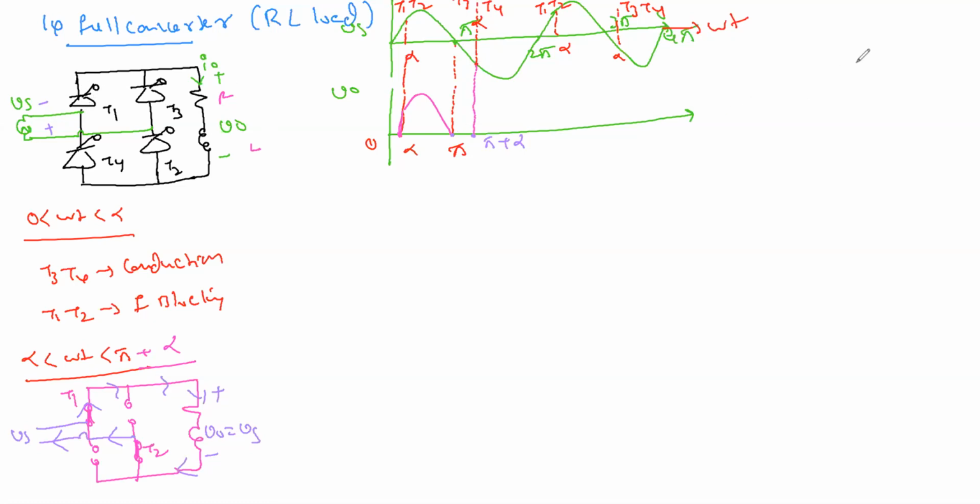With the inductor, we have seen this only if the inductor is taken. Look here now, one SCR complete, inductor is taken here. Now what we have observed? This is Vs, V0. V0 is a sine waveform which is Vs. After pi also they go into conduction. That's what I told you, beta is 360 degree for an inductor. Understood? 360. Therefore the inductor is kept, it makes the current continuous.